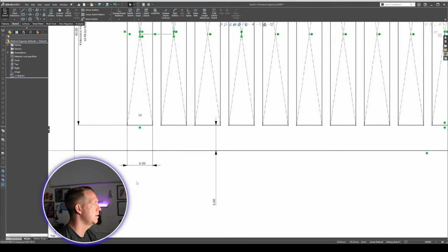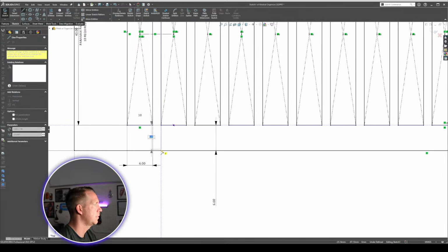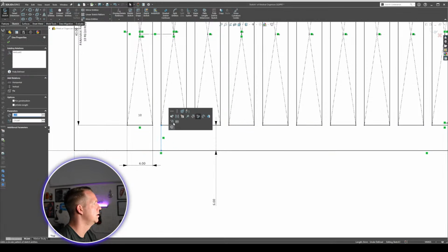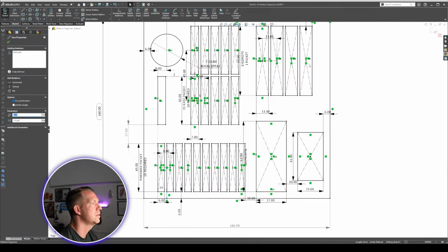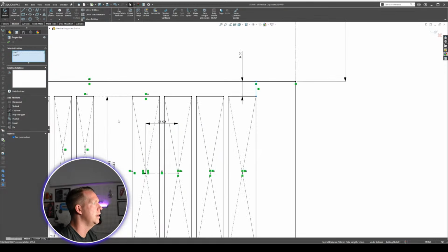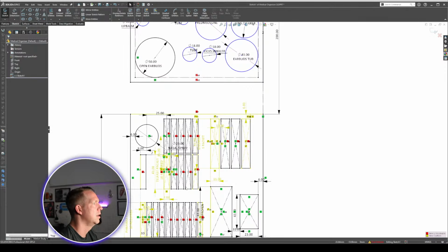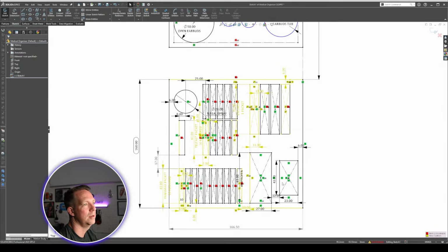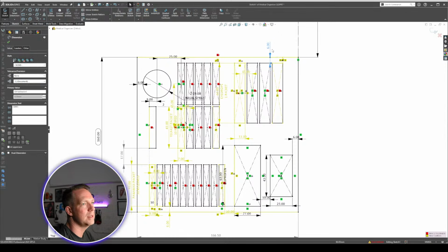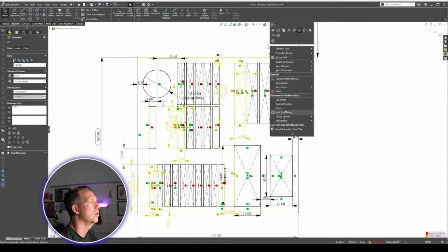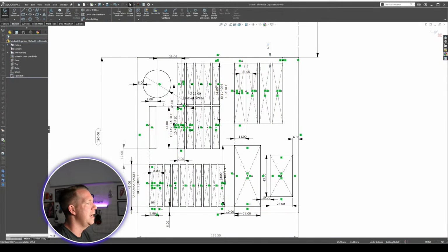We're going to do the same thing over on this corner. Let's just do it here. Make this line for construction. Now I'm going to select both lines and give them equal constraints. Now, once again, it's over-defined my sketch because I've got 2 dimensions, I've got 2 lines, and they're both equal. Too many things, even though they're the same dimensions, trying to control the same thing. If I grab this number 6 dimension up the top here, right-click it, and go driven, now everything can work itself out again.